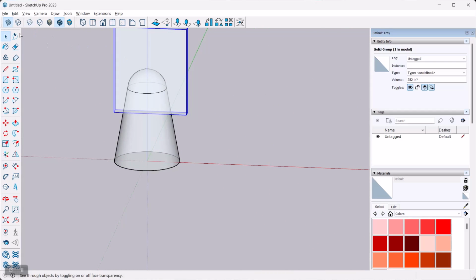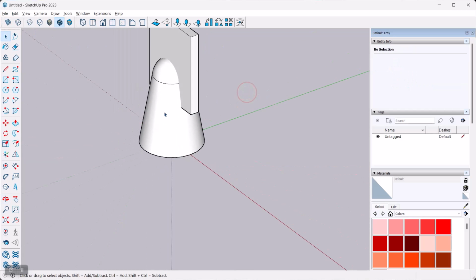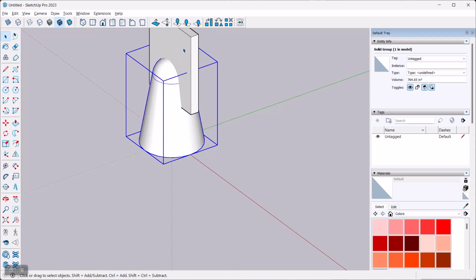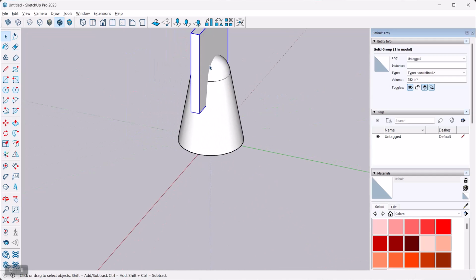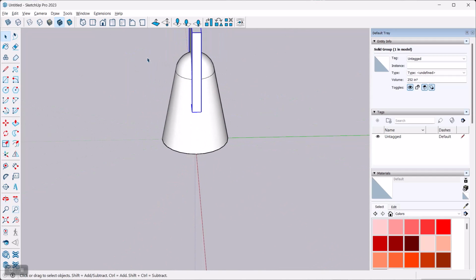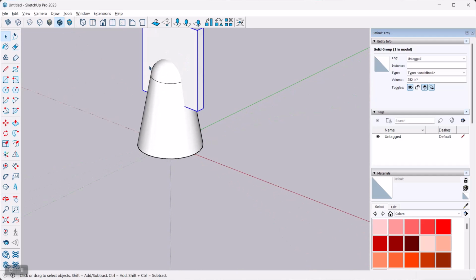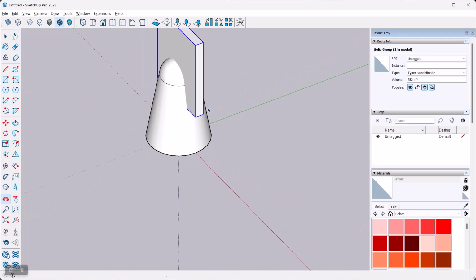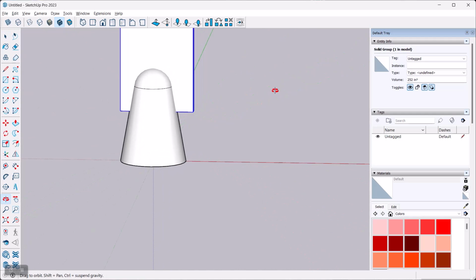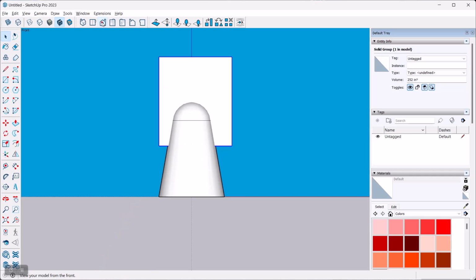and then we're just going to turn X-ray off so that it's clearer. We're going to have positive geometry right here, and then all the cutouts, and including tolerances, obviously. If you need a little bit of tolerance here, you're going to add to whatever the steel plate thickness is. So all of that's going to be a negative geometry that's going to be cut out from over there. Okay, so there's that. You could start cutting things if you want to, or you can now again keep modeling.